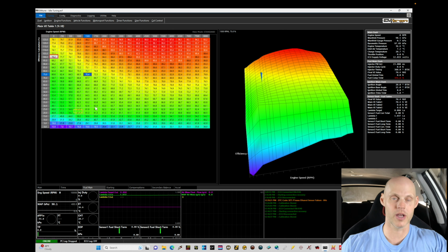So we know we have our equation: fuel mass is equal to air mass divided by target air fuel. We've established our target lambda, target air fuels, in our target lambda table. We have the injector data sorted out. We have the flow rate and the dead time sorted out. So what we're left with here to really determine is if our VE values in here are an accurate air mass representation. Now we're going to use our lambda control feedback.